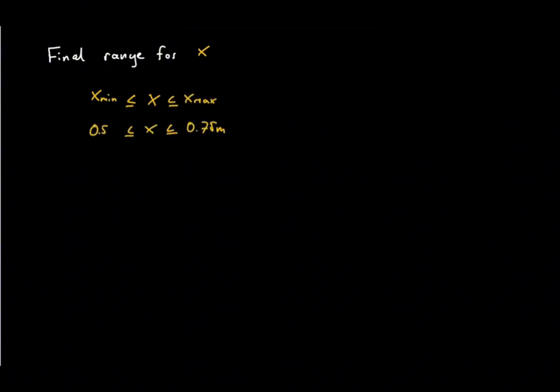Therefore, the cable can be attached anywhere between 0.5 meters and 0.75 meters from the wall while maintaining static equilibrium. The most important lesson from this problem is that static friction does not have one predetermined direction. Its direction depends on the motion the body would undergo without friction.